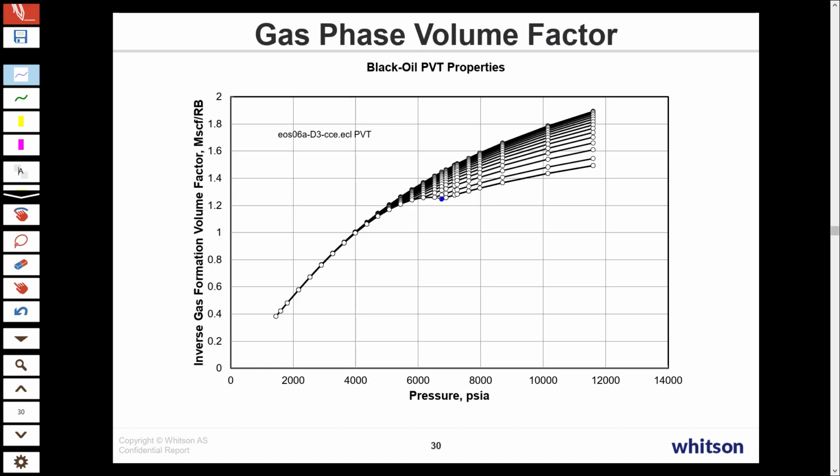But instead, the little BG increases as you go below the dew point, because the gas composition is changing so much, it overcompensates for the pressure reduction, and you actually get an increase in the little BG for a couple of pressures before it starts going down. If you take the incipient, that initial dew point gas, and you go to higher pressures, then all you're seeing is compressibility factor. And you get this basically little BG behavior here of the undersaturated initial dew point gas.